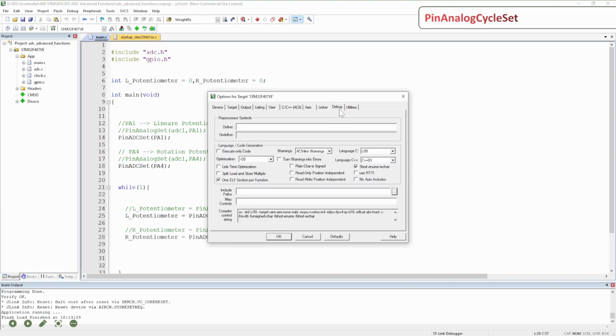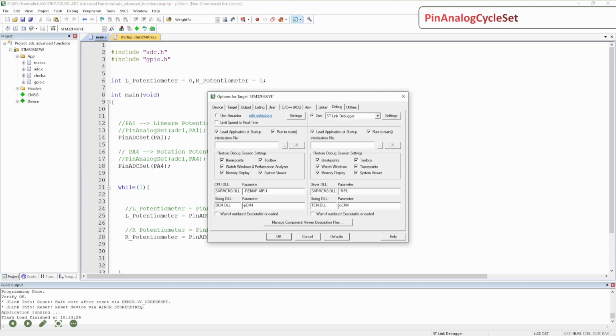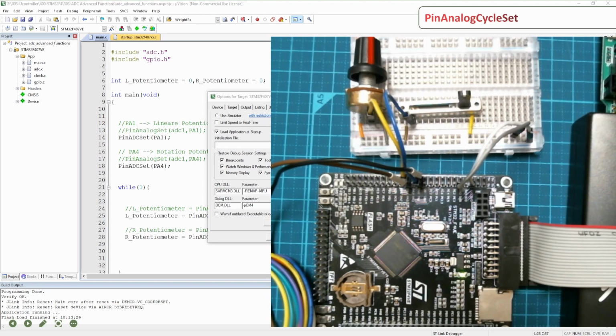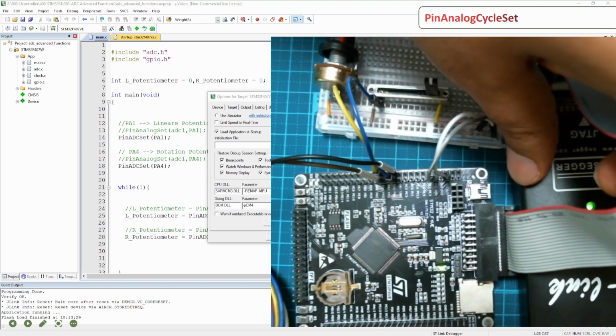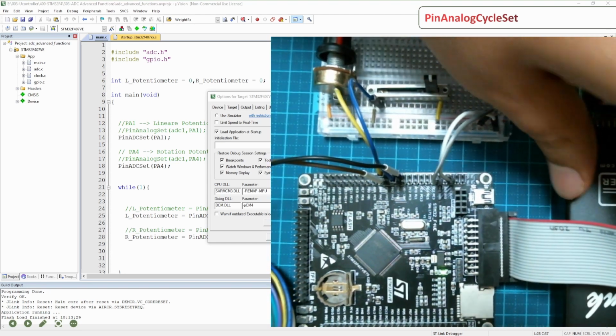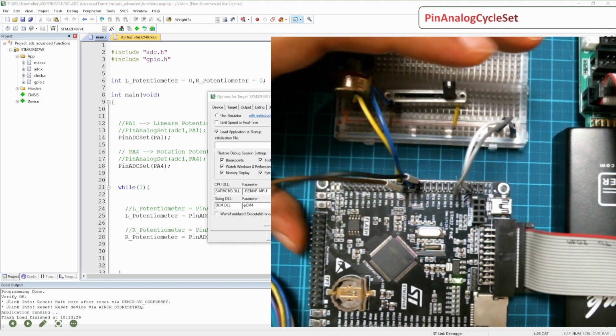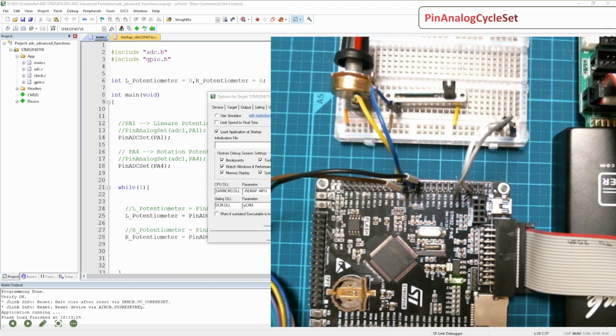Also in this example, something worth noticing is that I'm not using a normal ST-Link. This is a choice, so you know that we can use a different type of code loader, and this one is called a J-Link. A J-Link is a more general code loader, better adapted for whatever microcontroller with an ARM microprocessor.